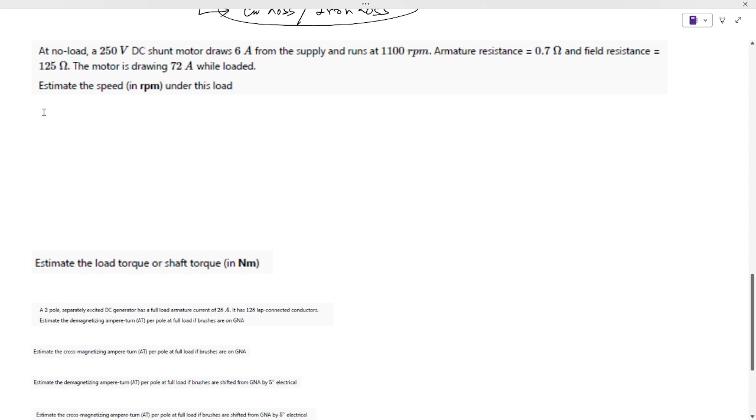Okay, at no load, if suppose there is no load to the motor, where is the input power going? Can you reply this? Sir, friction losses. Or I may say that is feeding the constant losses, friction, windage, and so on. Okay, all sort of losses. So those are categorized under constant losses, or you may call them rotational losses. And so the machine is under no load.